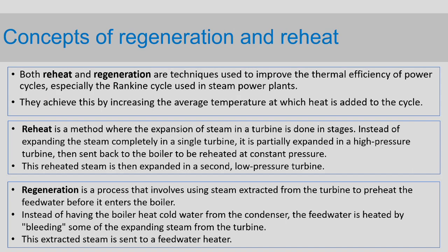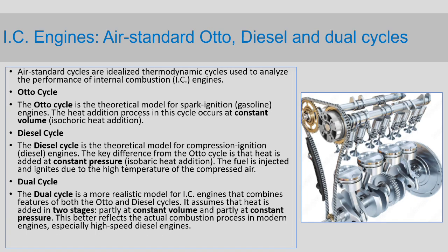Next topic is concepts of regeneration and reheat. So both reheat and regeneration are techniques used to improve the thermal efficiency of power cycles. So reheat is a method where the expansion of steam in a turbine is done in stages. Regeneration is a process that involves using steam extracted from the turbine to preheat the feed water before it enters the boiler.